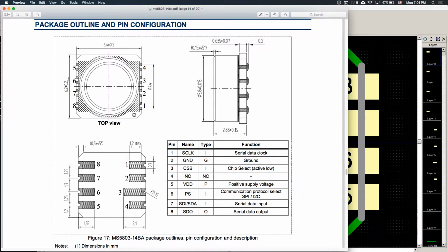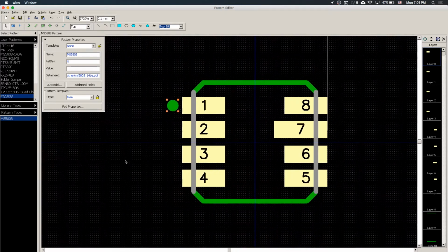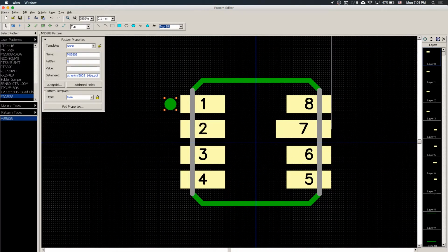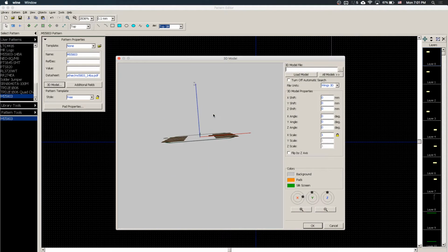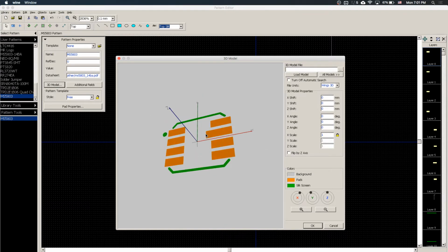I'm just following it, but if you want to make it a square, I don't think the space saving will be enough. Rather, when you solder this on, there will be a square versus the chamfer that already exists on the chip, so there might be a discrepancy that I usually try to avoid. So the last thing is we add a dot to this, and we can see how this pattern looks in 3D space.